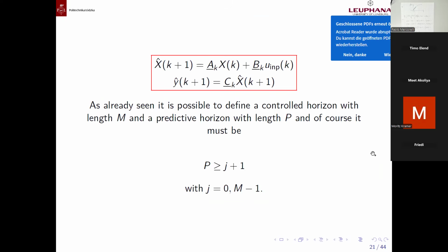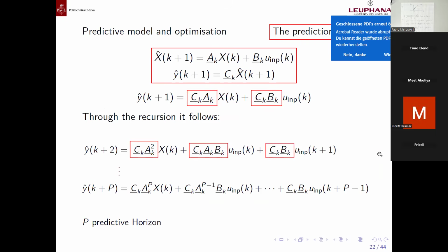Again, here we have the control horizon, which is basically in our system equal to the prediction horizon. It could also be different, but again, the control horizon is less than or equal to the prediction horizon. The last slide, and then next week we will conclude the presentation. The system now is known. I already clarified that also here is a prediction. And we can see explicitly, not only for both states, the prediction of the omega, including C. I have the omega here, the predicted omega.